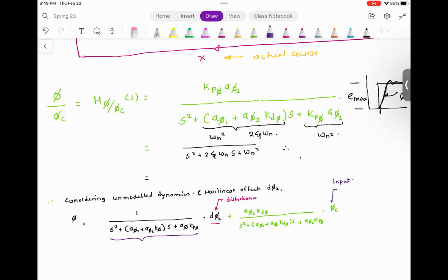Yeah, Ki times the error times delta T is the controller input. Right. So basically, because time is increasing, the integrated error will keep on increasing. Well, it depends upon the type of disturbance, whether it's a short duration disturbance or a continuous disturbance. It completely depends upon the type of disturbance. Sometimes you can have a ramp disturbance. You can just have a step disturbance. For example, loss of fuel. Fuel is gradually reduced. So basically that error, the modeling dynamics, is gradual.